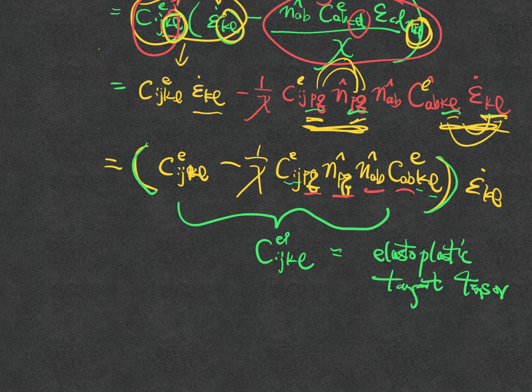If the eigenvalue is very low, then what it means is that actually it's very easy to... Sorry, let me correct it. If the C^EP has a very high eigenvalue, that means that you can change the stress easily by changing the strain. Okay, you see what I mean?